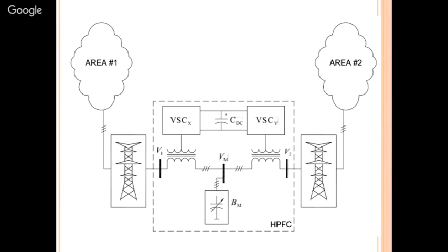An advantage of stability. Now there are various topologies of HPFC which are available and which have been proposed. One of the topologies which I am going to explain today is this. In this case, what they have done is they have taken one shunt capacitive control capacitance, and in addition to that there are 2 series VSCs which are actually half rated. So you might ask me a question: you have already used 2 VSCs in this case, so how is it different from your UPFC?